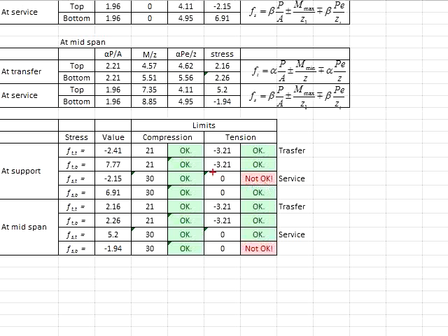If flexural cracks are allowed within the member, you will need to check for the fctm limits, and the provided amount of reinforcement bar needs to be at least greater than As,min. The calculation of the provided As is inclusive of the prestressing steel area and non-prestressing steel area.